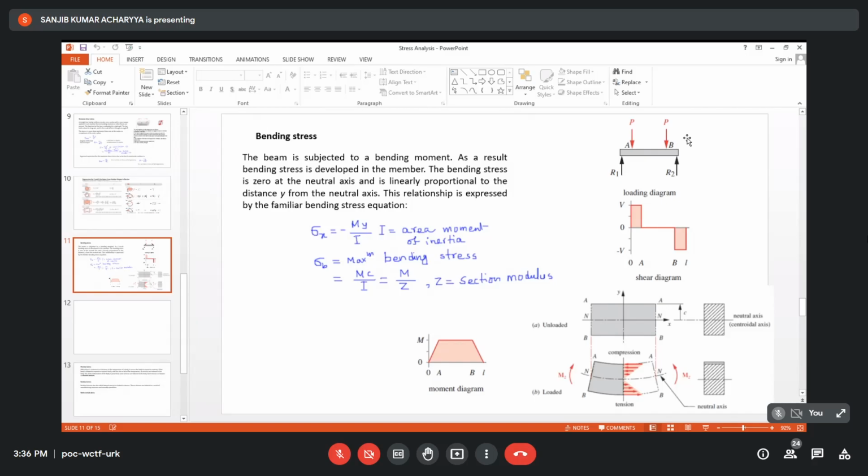If it is axial and bending alone, I have no problem because these two stresses are normal in nature. They either can be subtracted or added and can get a final normal stress value and compare with the material permissible normal stress. But when torsion is present along with either axial or bending or both, then one stress is normal in nature, another stress is shear in nature.